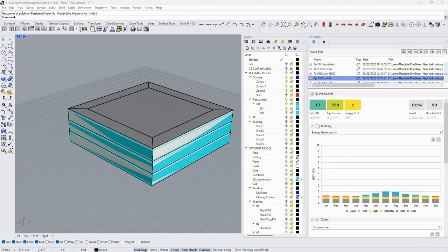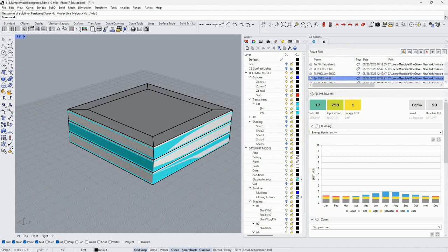In a previous video, I implemented natural ventilation as a way of decreasing our site EUI. We were modeling this medium-sized office building, 125 feet long, about 40 feet tall, 3 stories, curtain walls, so a lot of glazing. We developed a really good envelope: Passive House level insulation, very low infiltration, and got to this low site EUI, but we still had a cooling load, so I implemented natural ventilation to try to get rid of some of that, which we did.